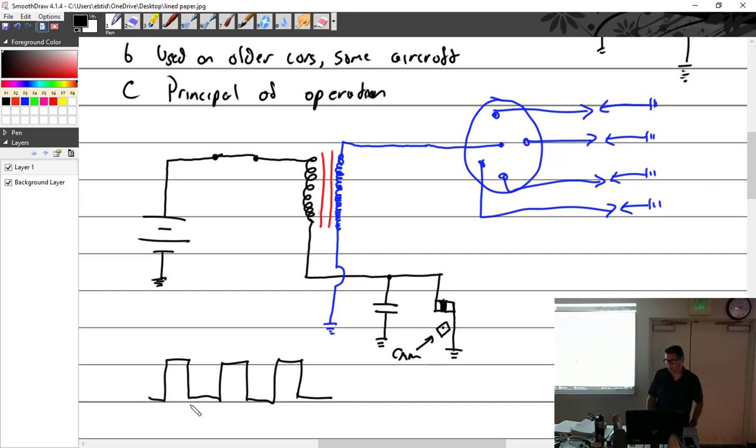And so when the primary expands, whoop, points open, sudden and rapid collapse of the primary, which had the lines of flux going across the secondary. We have flux movement across thousands of windings. We get high voltage, 18, 20, 20.